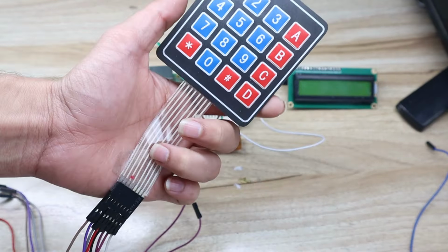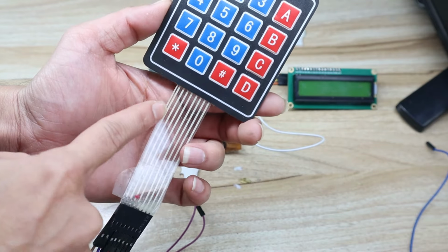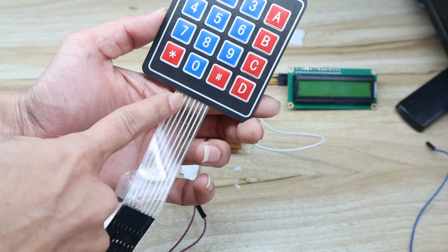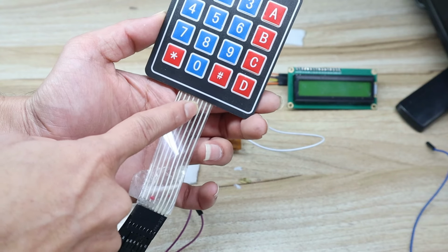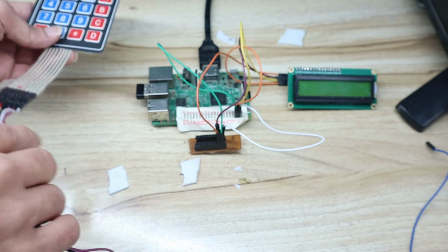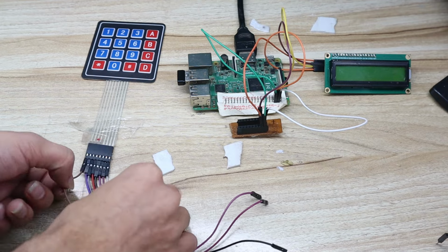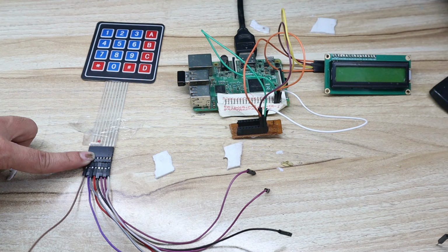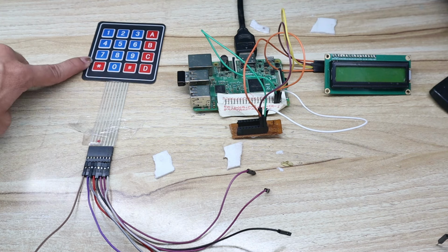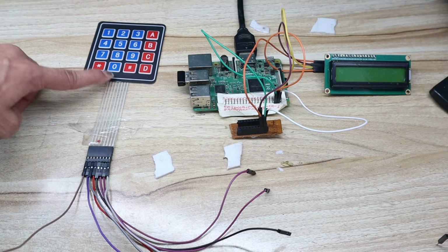keypad. So this keypad is very easy. The first 4 pins act as row pins, R1, R2, R3, R4. Then the next 4 pins act as column pins, C1, C2, C3 and C4. Okay, so a very easy connection. You just have to connect one by one. So the first pin you should take is the R1 pin. The R1 pin starts from this star, you can see the star, this is the R1 pin. Okay, R1, R2, R3, R4.